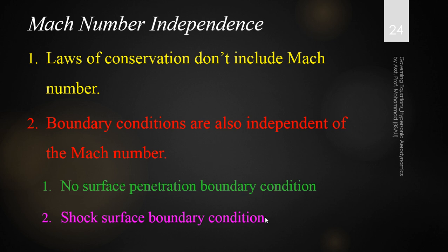So as a whole, we saw that even the conservation laws, the governing equations, and the boundary condition equations are free from the Mach number when the Mach number is in the hypersonic regime. So the entire flow is actually free from the Mach number. Mach number is not affecting it.